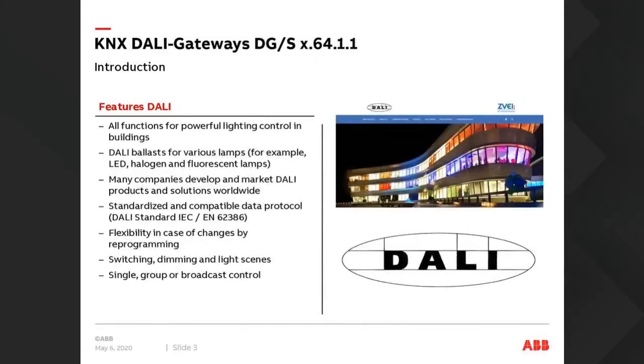Okay, so the features of DALI. I don't know how much you know about DALI, but it's the Digital Addressable Lighting Interface. DALI came around as an evolution of lighting control systems. It's controlled to the standard 62386, and it's evolved even at this stage. The problem with DALI was that when it was first released, it wasn't like KNX, where the rules were set in stone and a released device had to comply with them. More so, they were guidelines.